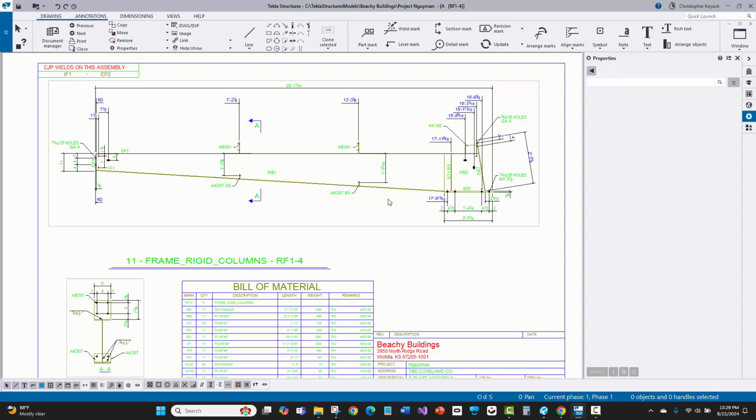You use a combination of the drawing settings that I've created as a good starting point, but then you know how your job is set up and what the similar assemblies are, or you can just use Tekla to do the smart create. If you know that you spend a lot of time, more than a couple minutes, to clean up a drawing, then sometimes it makes sense to delete the drawings that the automated rules did and try the smart create out and see if it works, and it's going to save you time.